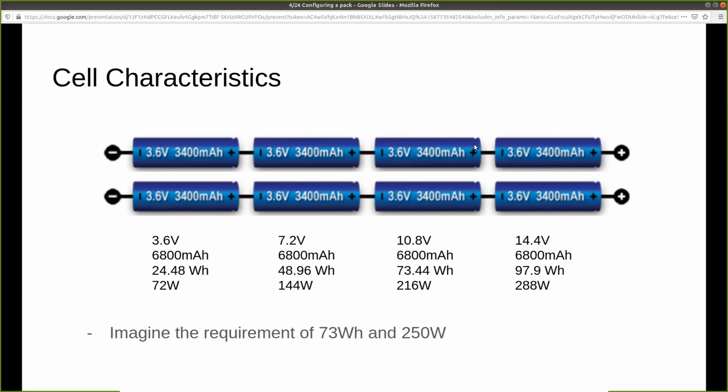And that's because as we're adding energy and power to this battery pack, we're getting energy faster than we're getting power, and that's limiting our power if we stop there. Or we could add 2 more cells, and now we have enough power, a little bit extra, but we really have a lot of extra energy.